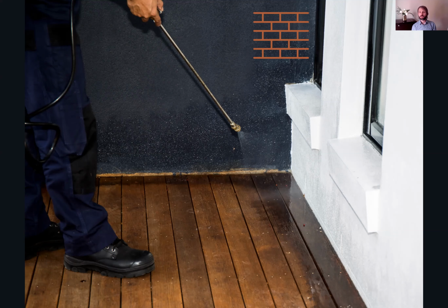So installing a steel mesh barrier termite control system, a physical termite barrier, use solid concrete foundation, below grade masonry walls, install post-tension slabs, treat all cellulosic materials like wood framing with a borate pesticide that's safe, using non-cellulosic materials in the walls that won't be enticing to pests.